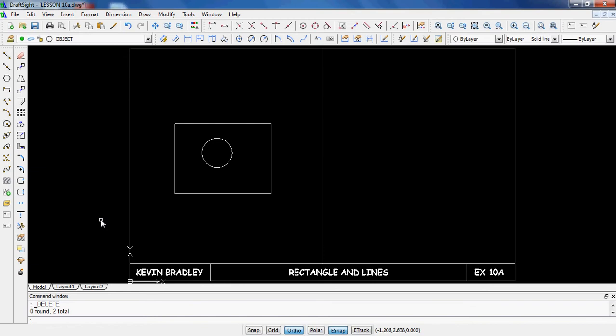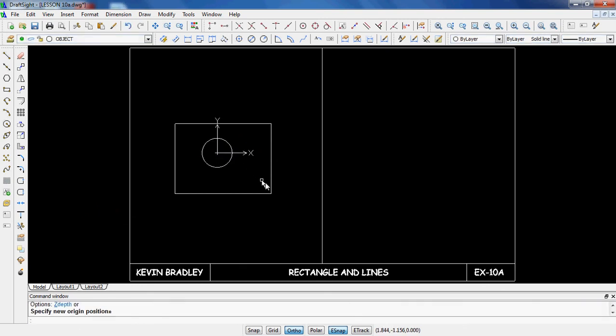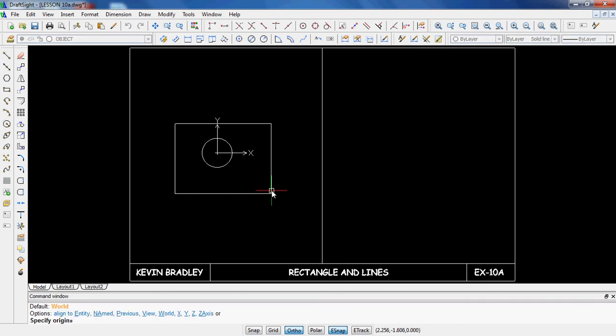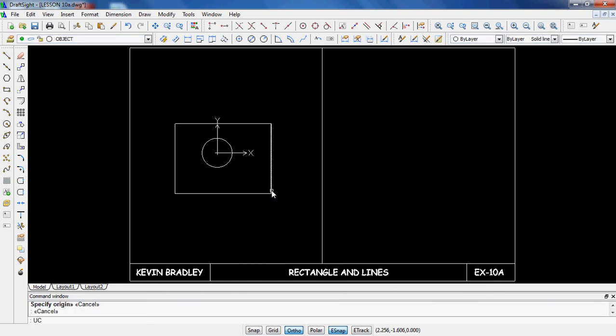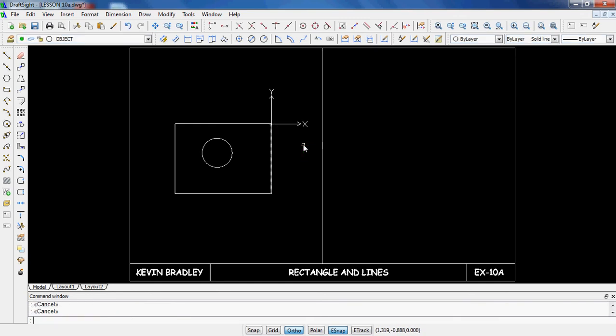Looks like you're moving the origin around a couple times. So generally it's just understanding X and Y coordinates as you've learned in algebra and being able to move the UCS around. The way that it's taught in AutoCAD is just hitting UCS enter and then M enter, and then specifying, like, if I want the UCS to be right there, then there it is. So you can do that, or you can type in UCS, or just click where you want it to go and then hit enter. Either way works. Just make sure you understand how to move it.